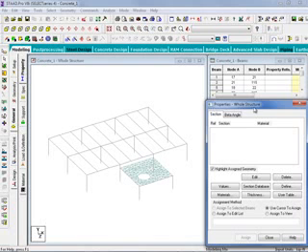Over in the Properties Whole Structure dialog, the two areas I'm going to use for this particular model is the Define button, that'll help me define my beams and my columns, and also the Thickness button, which I'll assign to plates in the model. Now before I specify the properties for my concrete beams and columns, I'm going to look down to my status bar and notice that my current input units are set to kips and feet. I would probably prefer entering the properties for my beams and columns in the units of inches instead.